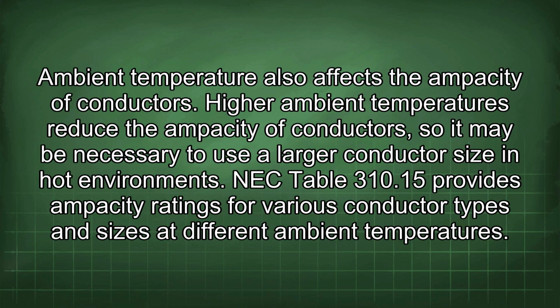Ambient temperature also affects the ampacity of conductors. Higher ambient temperatures reduce the ampacity of conductors, so it may be necessary to use a larger conductor size in hot environments.